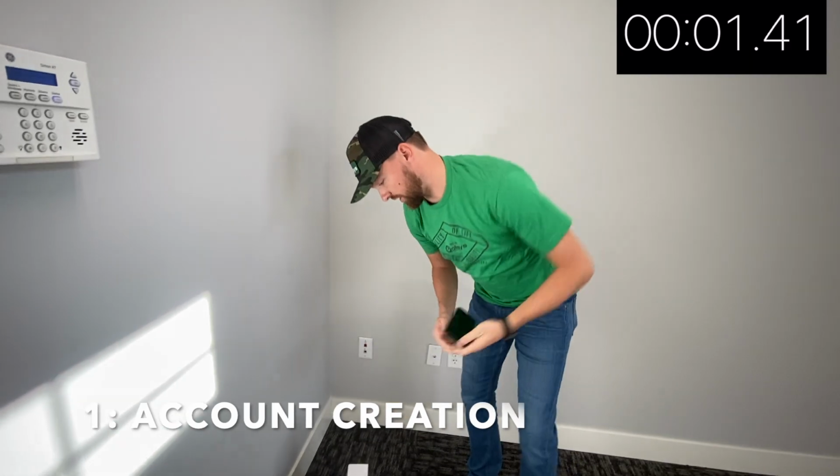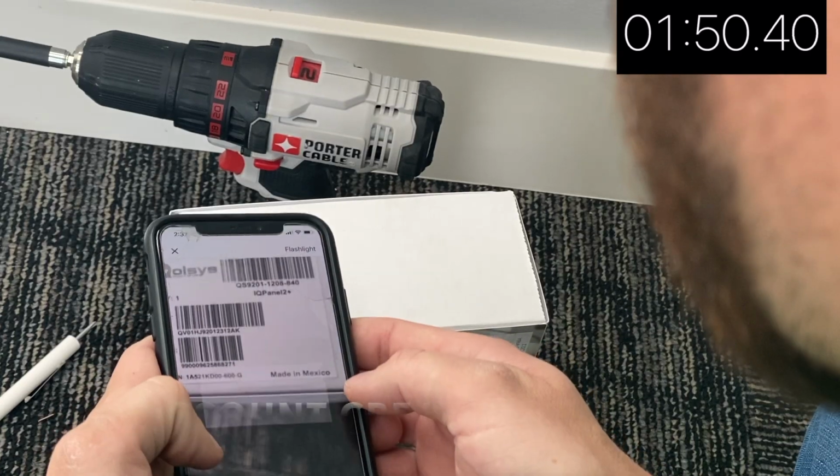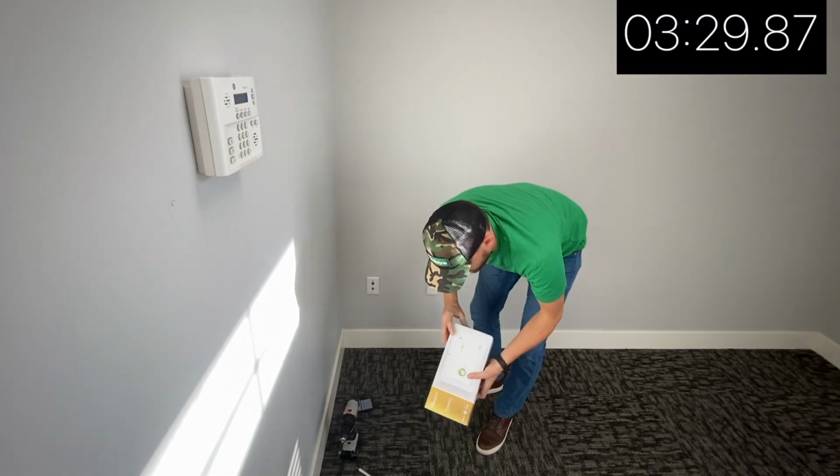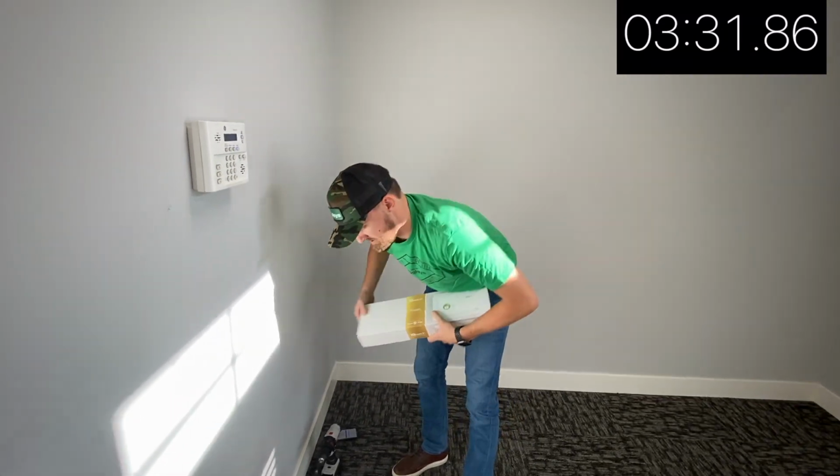I'm going to show you today how easy it is to take over an old Interlogix system using the Qolsys IQ Panel 2. I'm going to start with creating the account. Use my mobile tech for that. Now the account is created, I can get on with my install.